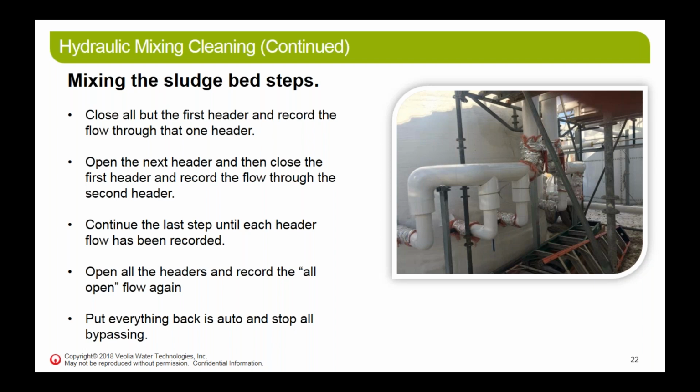You want to go through the heat exchanger, put the pulsing mixing valves back into auto, and put your reactor feed flow back into auto.